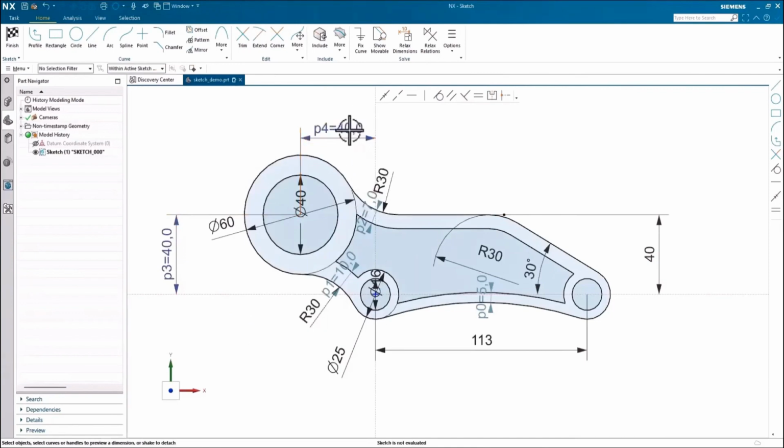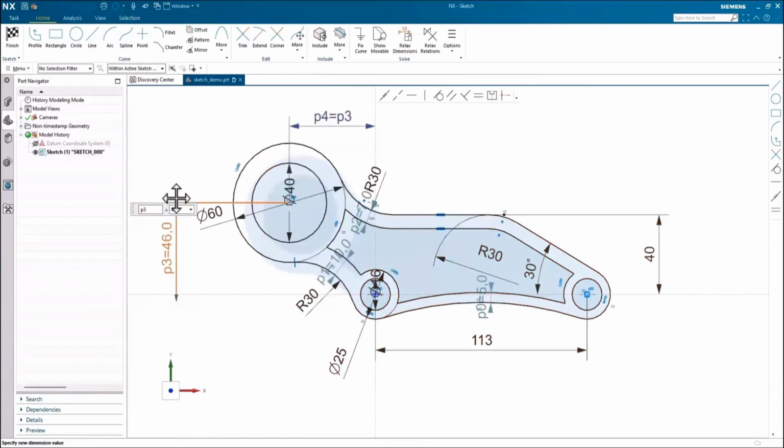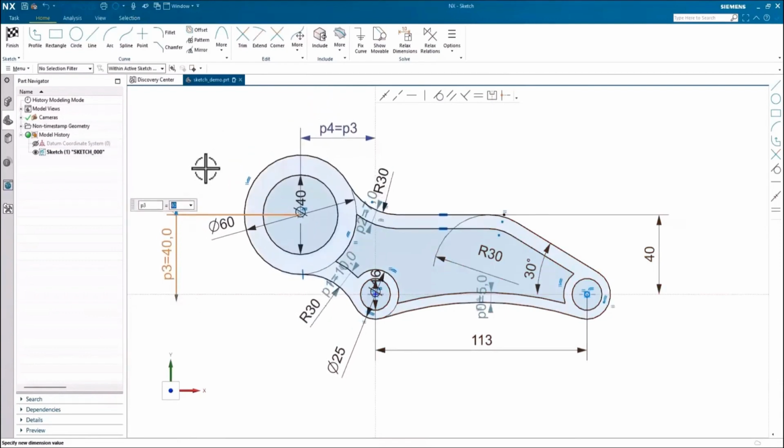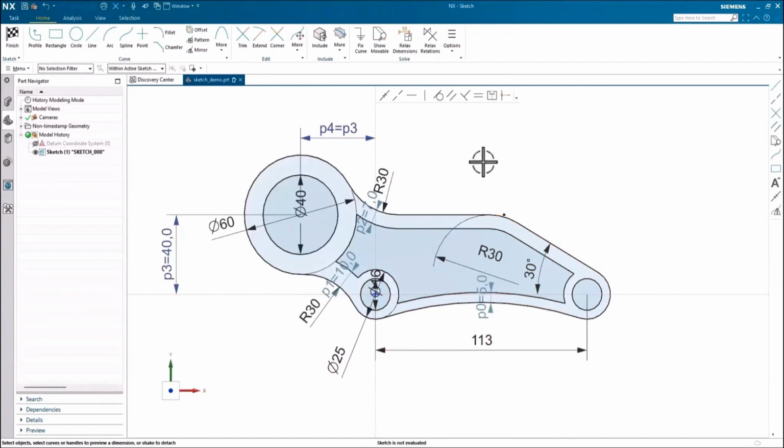But what you'll notice is, tend to go in and do the dimensions. And as I put in here, I put some expressions. You can do the formulas just like you did before. You have access to measurements, the expression system, just like we always have. Those are available to you inside the sketch environment. So you can see in that method, by making them equal or a formula, we're driving both at the same time.